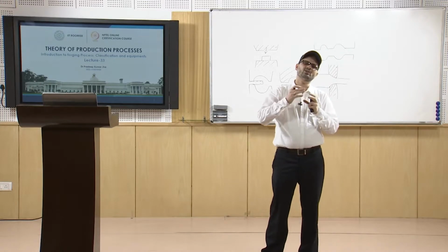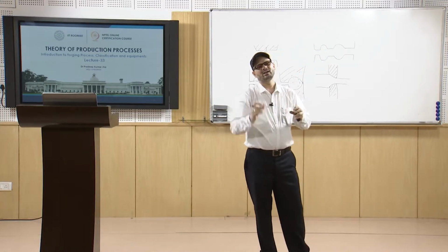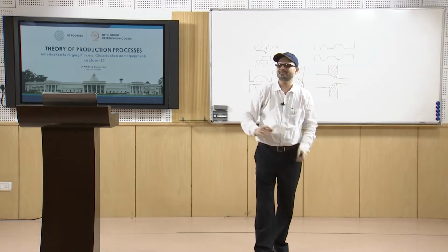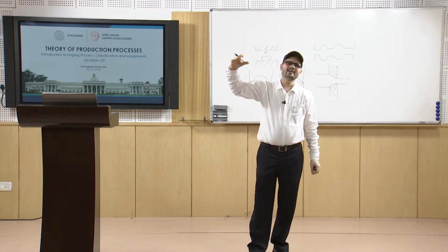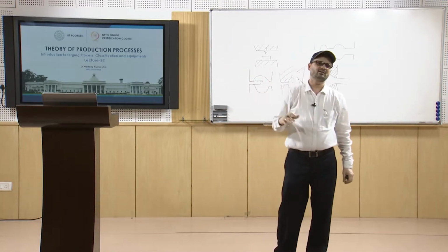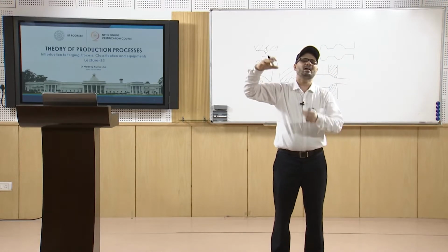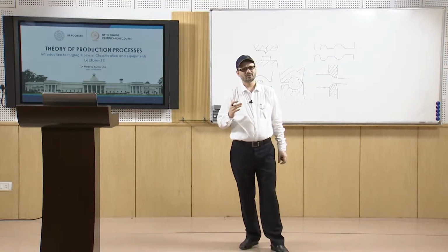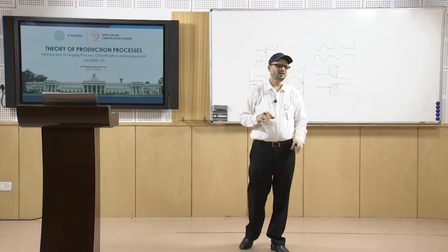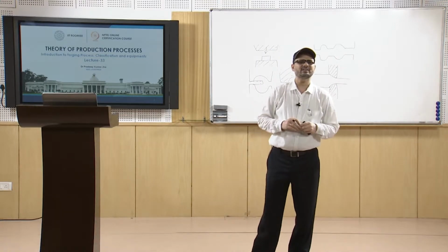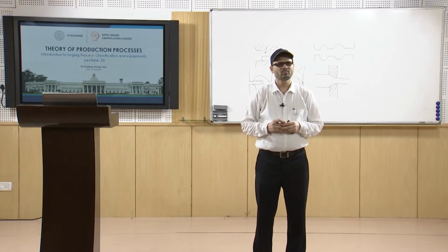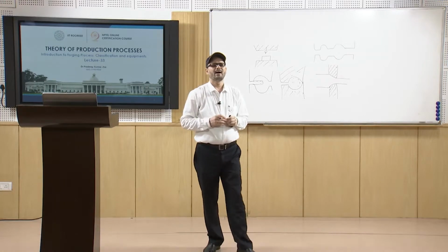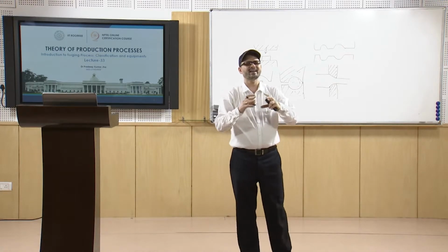casting, where extra metal goes in, once your runner or the riser which is connected with the casting gets filled, it means you ensure that the casting is completely filled, if the riser level is above that of the casting. Now, in this case also you need to ensure that none of the portion is unfilled. So, for that you have to provide certain extra material, and that extra material will come out of the cavity as a thin ribbon of metal.